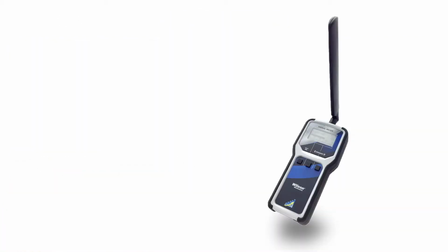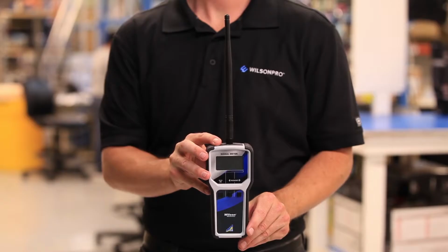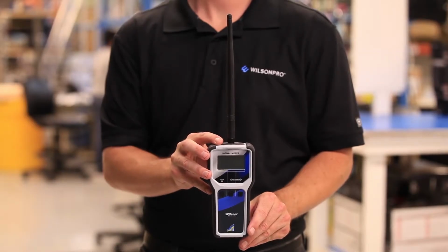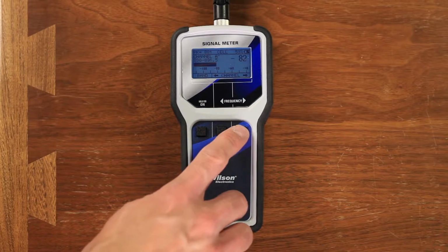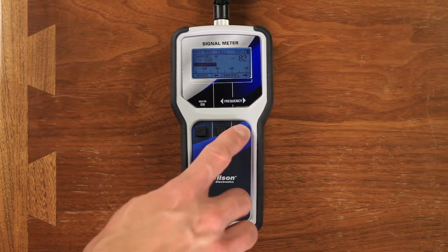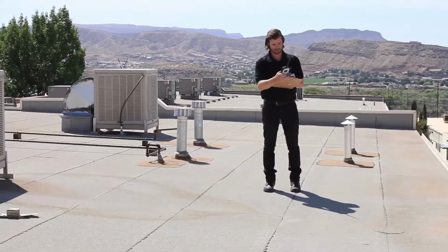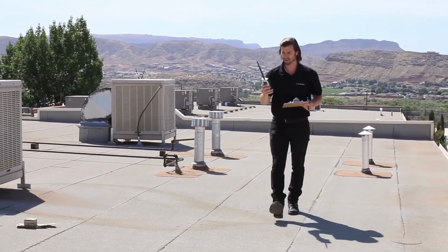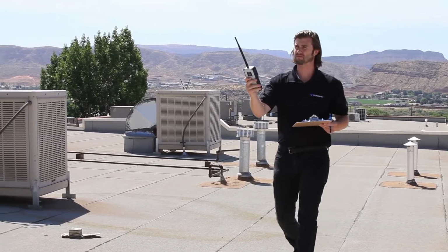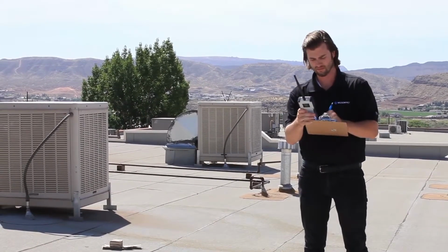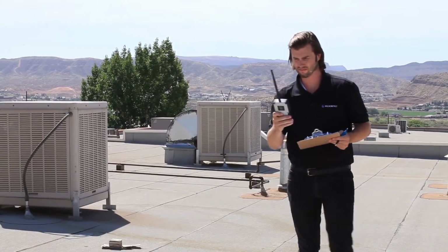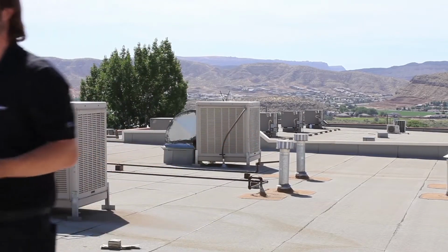When testing cell signals, we recommend using a signal meter instead of your phone in a test mode. Signal meters are great because you can cycle through all the various bands and frequency ranges on one device. Because carriers operate on different frequencies and you are installing a multi-carrier solution, the only way to ensure performance is with a proper tool like a signal meter. A signal meter also updates instantaneously, so you won't waste time waiting for the signal to update in each location.